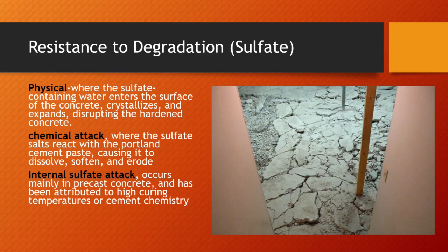And the unusual thing about concrete is if it gets into an open wound or it breaks through the skin, it keeps burning for days. It goes deeper and deeper and deeper. It really is a vicious material if it's not handled correctly. And there's various chemicals in that material.